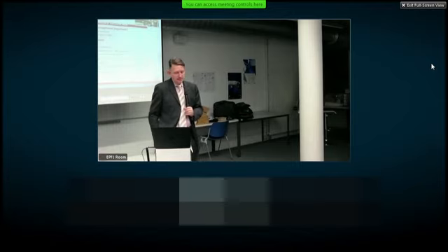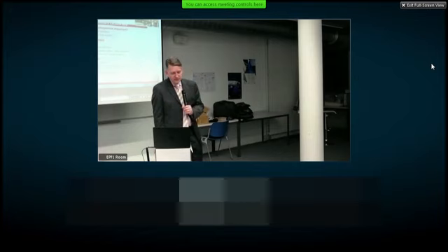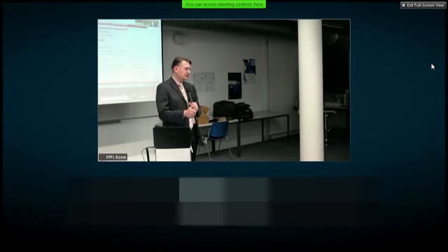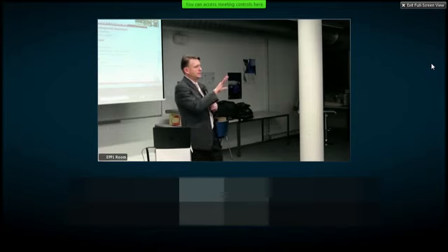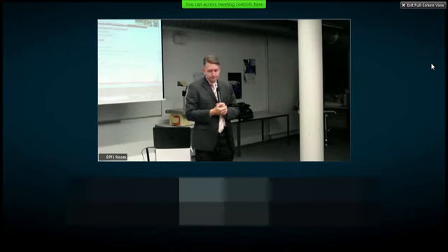Interface management has different aspects to it. So first of all, types of interfaces. There are many, dozens or hundreds of types of interfaces, but they can all be boiled down to the four canonical types: physical connection, mass, energy, and information flows. I've introduced you to the DSM, the Design Structure Matrix method, and that's where you basically decompose your system and you show it as an N by N matrix, and then you put all the interfaces into that matrix that you know about.